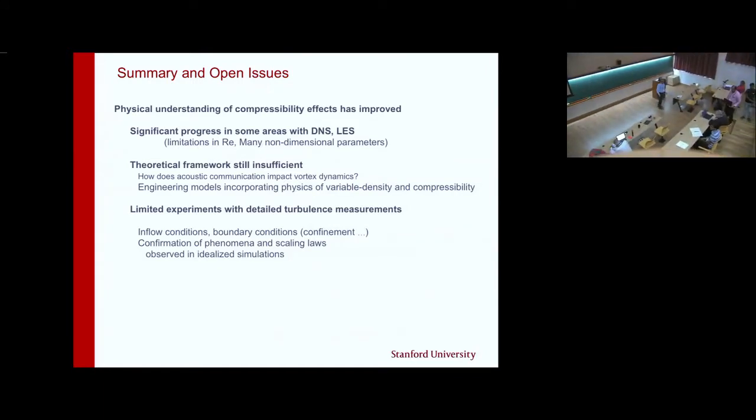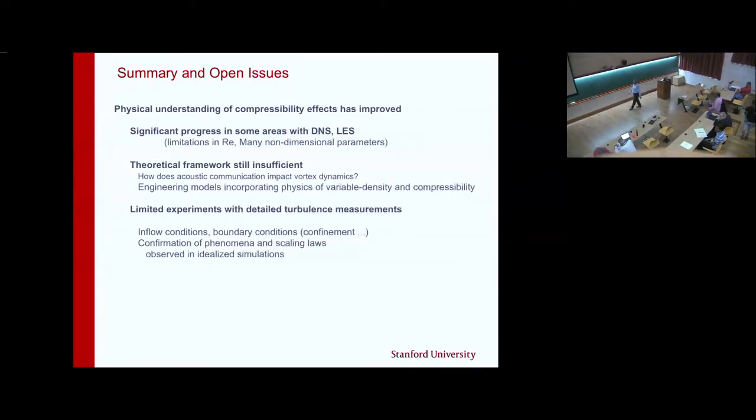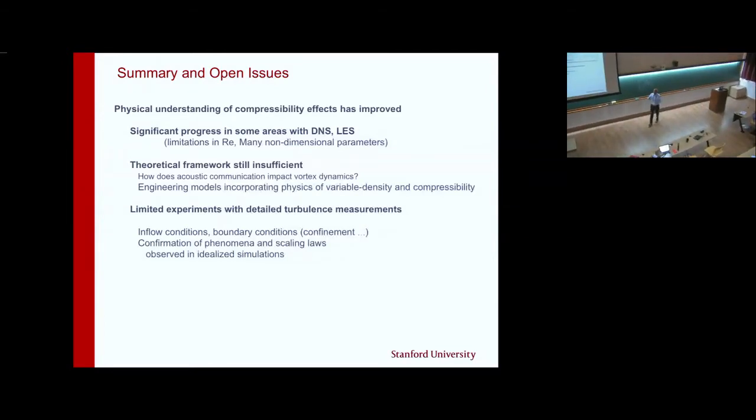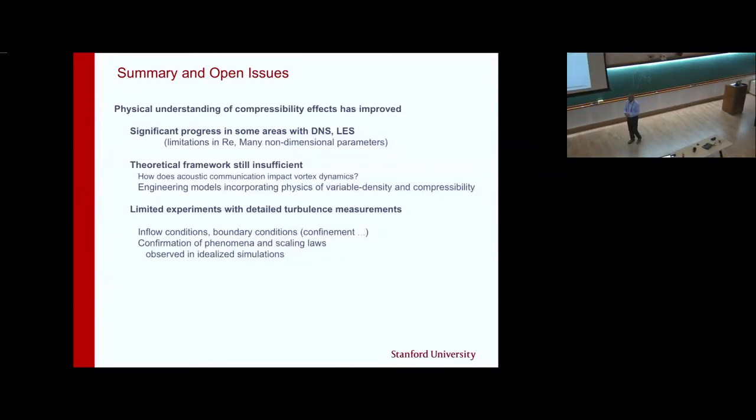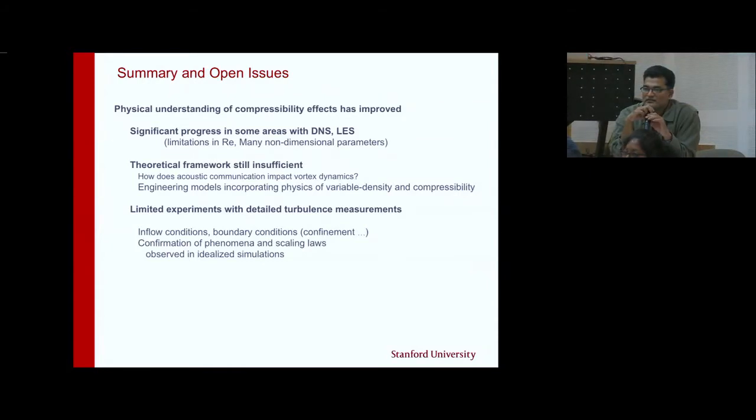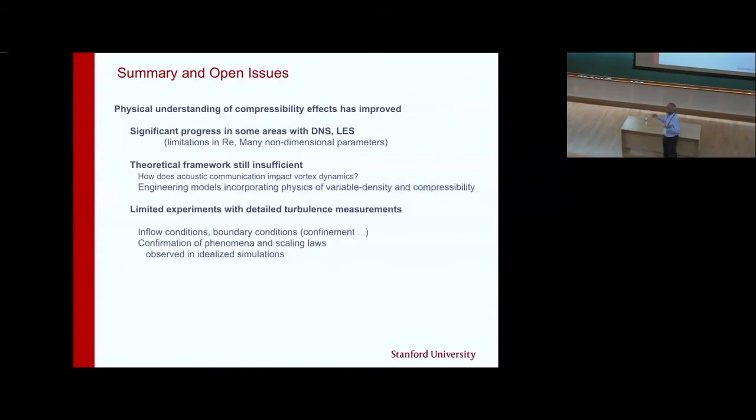So since we are running behind time, maybe one last question. This is from the mixing layer point of view. Are there any attempts to describe or explain the reduction in spread rate from the thermodynamic quantity statistics? Well, thermodynamic fluctuations and velocity fluctuations are coupled to each other in a compressible medium. And so it's not that one could explain it only from one point of view. It has to be a holistic explanation, and maybe we can talk about that more.